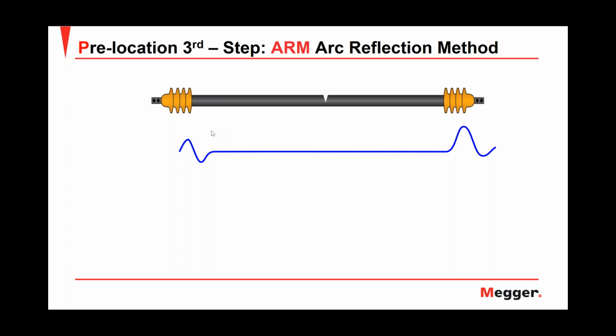Then this is what I will do. I will send a high voltage pulse of 4 kV, 4000 volts, and when the high voltage pulse arrives at the fault position, there will be an arc. The arc will have a duration of milliseconds, but it will be good enough for the second low voltage pulse of the TDR to find an arc, a different situation.